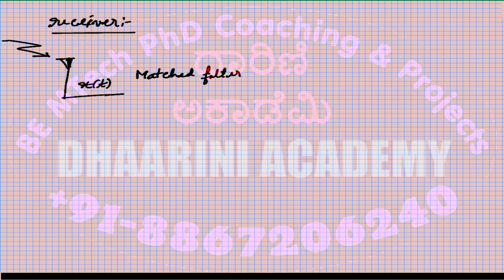So the matched filter is matched to the following equation, that is root of 2 by TB into cos of 2 pi fc t plus theta. To this you use a matched filter.